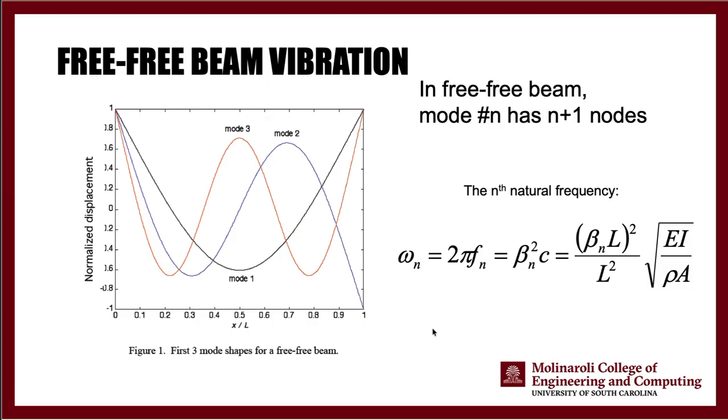So you essentially set your signal generator to the natural frequencies of the free beam theory, find the location of these nodes, compare those locations to the theoretical values that are given to you in the lab memo, and find the error, essentially. That would be the first step.